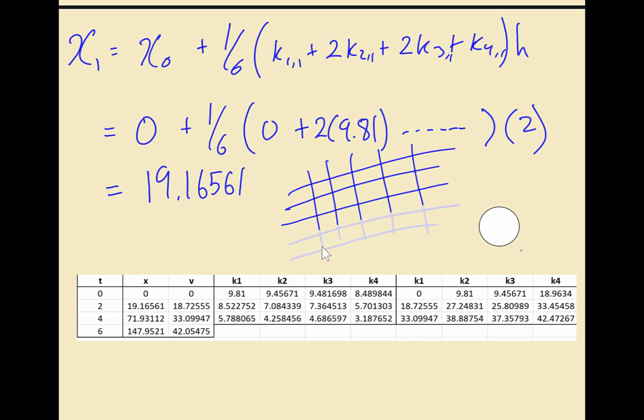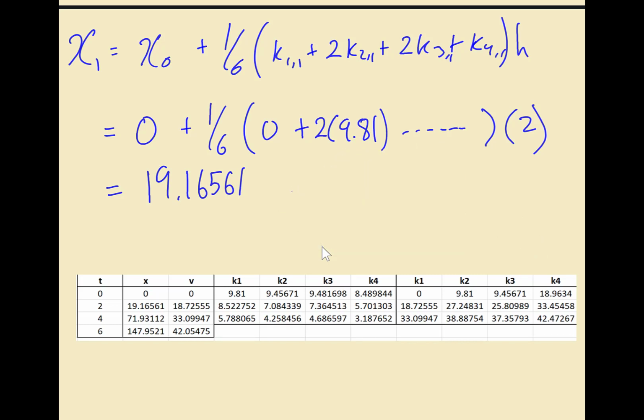And one thing, if you get to the point where you're using mesh sizes and you want to figure out, is my mesh size good? Then what you have to do is try out a mesh size. Let's say a mesh size of 10. Then try out 8. Then try out 6. Then try out 5. And look at the trend. Let's say the x-axis is mesh size here. And this is, let's just say, the value that you're solving for, okay? Whatever value you're trying to solve for.